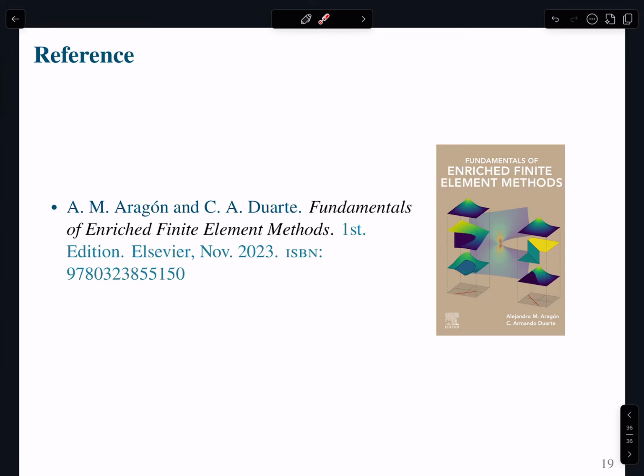In beams, we have a fourth order differential equation if you just take Bernoulli-Euler theory. Then when you balance the differentiability requirements, you get a second order derivative on the trial solution. And now you need to ensure that you have C1 continuity, otherwise you are dealing with a broken beam, right? So you require not only the transverse displacement of the beam to be continuous, but you also want the rotation of the beam to be continuous, right?